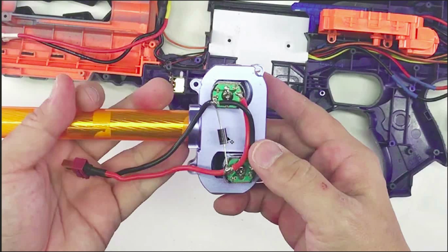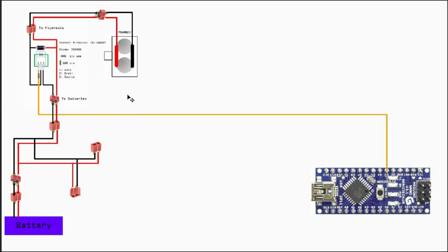And by the way, these 2 pieces of green thing that you see over here, basically they are just capacitor plates attached to the motor to reduce the electrical noise. So if you are dealing with microprocessor things as such, I believe it's a good idea to remove all the electrical noise as much as you can. And if you don't have this kind of plate, you can buy your own capacitor, whereby you'll see later on when I show the pusher mechanism how it works.